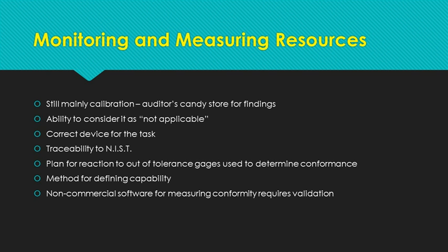One of the ways I see clients avoiding the need for retesting is to use gauges with a higher precision than is necessary. If the gauge is found to be slightly out of calibration, the company can show it would not affect product conformance. This still shouldn't create the situation of using a micrometer for a ruler. All devices used to determine conformance must be evaluated to ensure their continued fitness for use.